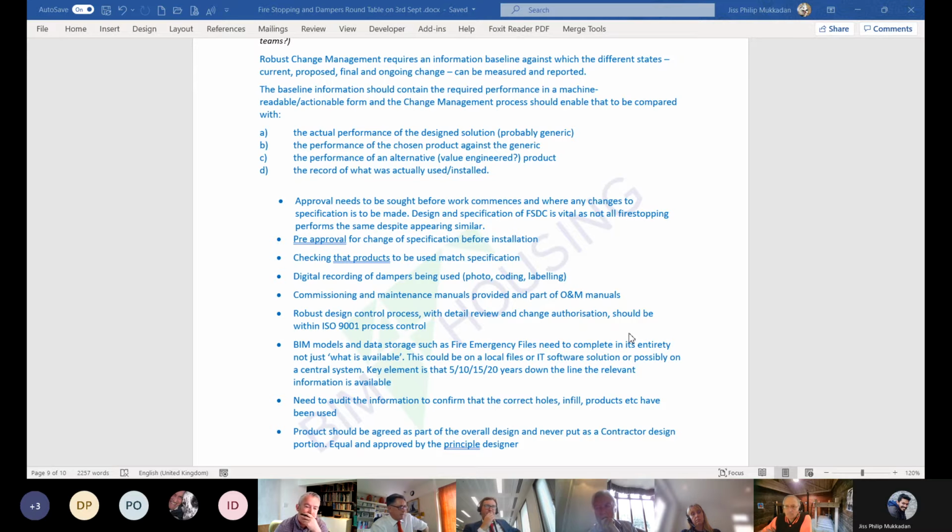if somebody tests it, then as Paul just said, it becomes complicated because your field of application isn't very broad. So if you had a 350 diameter hole and you stuck a 300 damper in it, that would be the maximum size you could go up to. You couldn't suddenly say, well, if I go bigger, it'll work, because you're not allowed to do that. And if the beam thickness changes or it's non-castellated, then you're in another question, aren't you, Paul? Because it's different. Yeah, it's different.